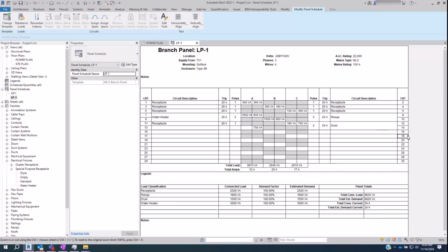Since I know this client and they like playing around, I will probably stick with a 30 space panel board so that they can put whatever they want out there: receptacles, feeding a wellhead, half a dozen other things. I'm definitely not going to put a 42 space panel board out there because they just don't need that many. And while yes, 18, 30, 42, 60, and 86 are the most common, there's still a couple more out there, the stair steps of quantity of spaces.